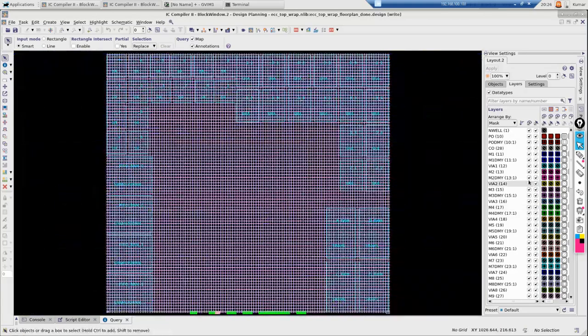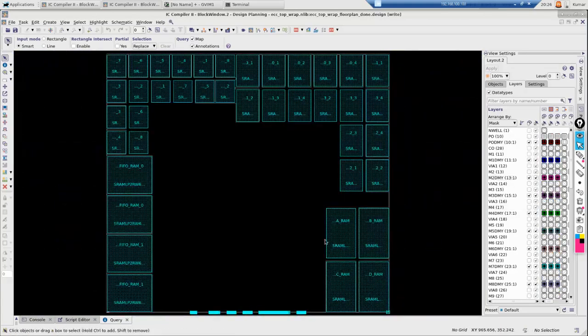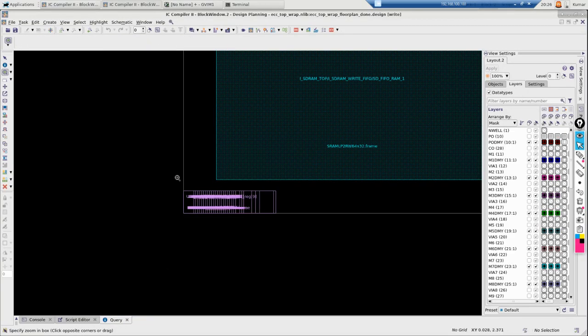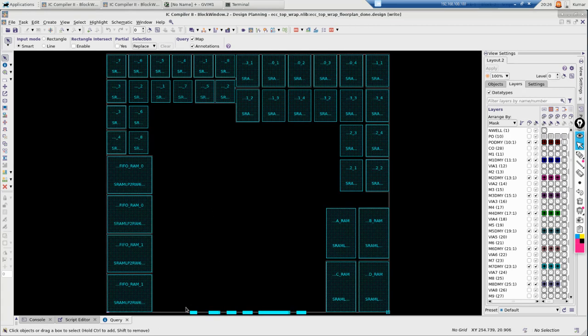Okay, and if you look at your standard cells, all those 52K cells were sitting down below. Now see here, they are all still sitting here. We have not placed them internally yet. Only the big cells we have placed, and then these are all your IO ports that we have placed. Now how do you place these IO ports, what precautions you need, all of that we will take care of during the floorplan itself.